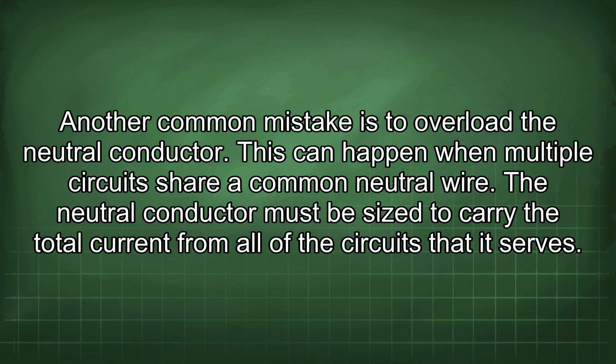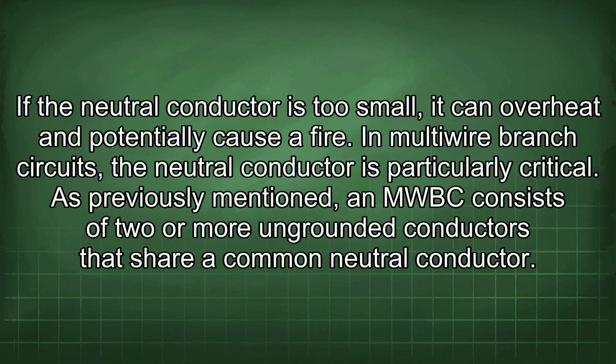Another common mistake is to overload the neutral conductor. This can happen when multiple circuits share a common neutral wire. The neutral conductor must be sized to carry the total current from all of the circuits that it serves. If the neutral conductor is too small, it can overheat and potentially cause a fire.